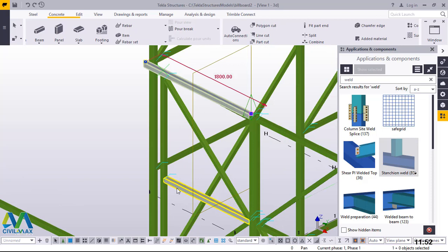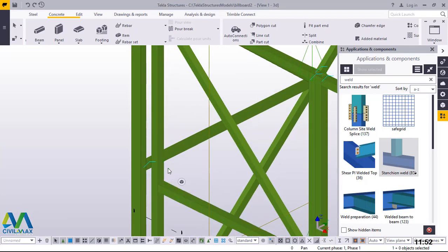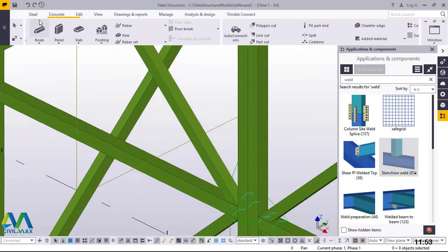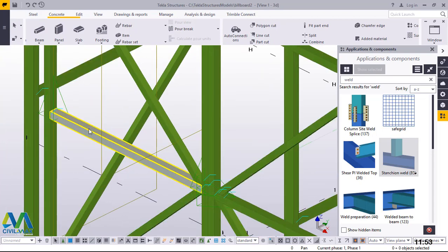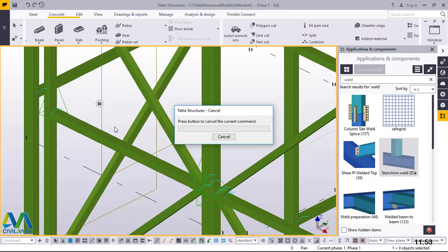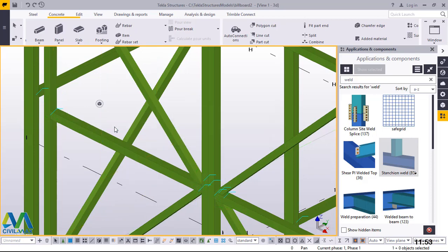I'll do the same thing here and click on that, delete that and give it 1800 and enter that. It will not move because it has been restricted with that dimension. I'll undo that once again and come here and click on it, then come here and mouse over this text and click on that and enter on the keyboard. It is not accepting. We'll redraw everything here so that everything gets refreshed.